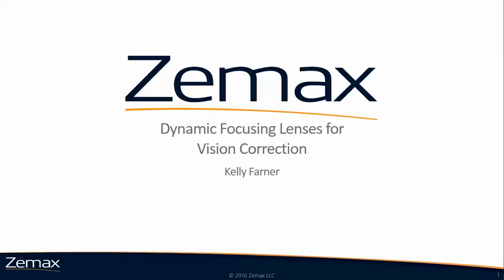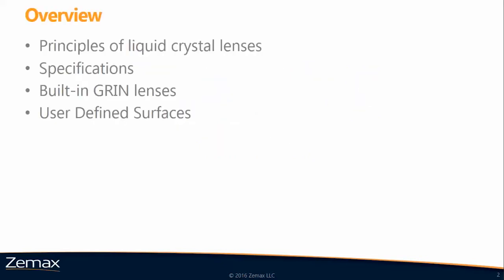Zemax, and I'll be discussing dynamic focusing liquid crystal lenses and how a user-defined surface can be created for OpticStudio to simulate these effects. Through the course of this webinar, I will introduce the principles of liquid crystal lenses and their dynamic focusing capabilities, derive specifications for our final system, briefly address the built-in gradient index surfaces which could be used to model a liquid crystal lens, and finally, guide you through creating a user-defined surface for this application.